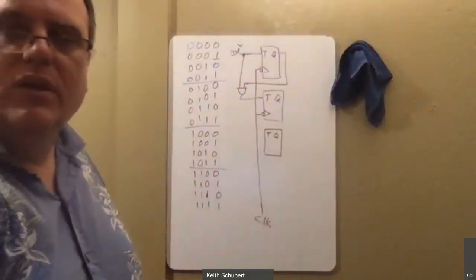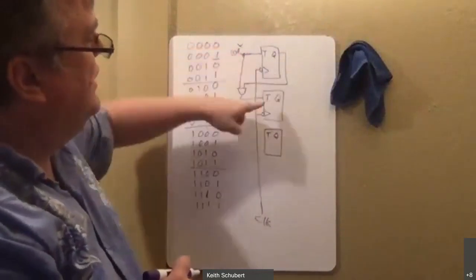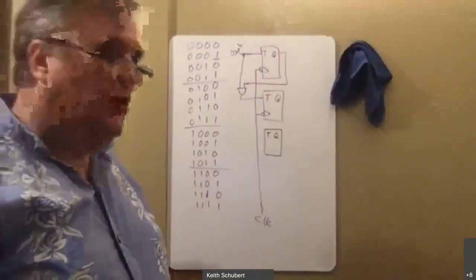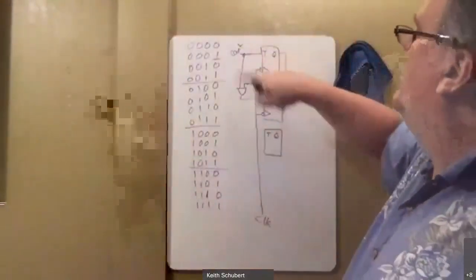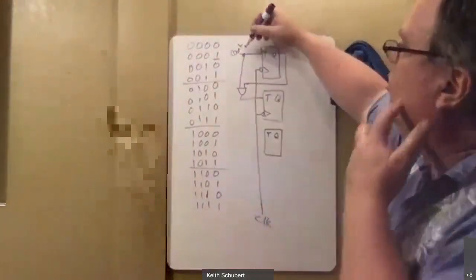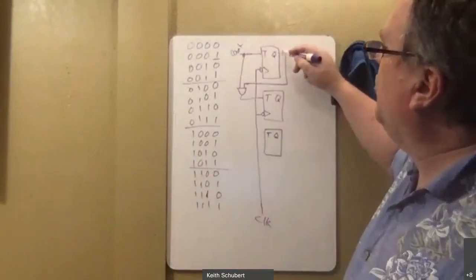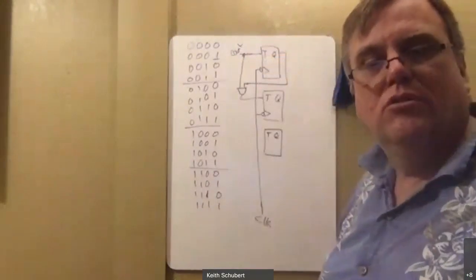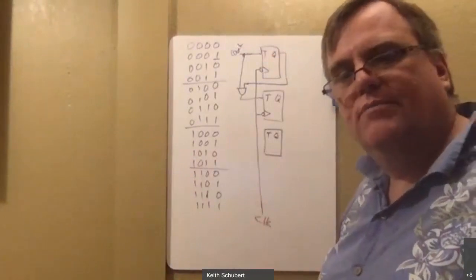All right. So we add this extra one in here because without this, these later digits are going to just run as fast as they can. If you want that, then that's awesome, right? You just put the synchronous thing, you put a 1 in on that T and let it go, right? But if you want to have a slower count, you need to say it's at the point where it should increment, and I do want it to increment. Right? So does that extra addition make sense?